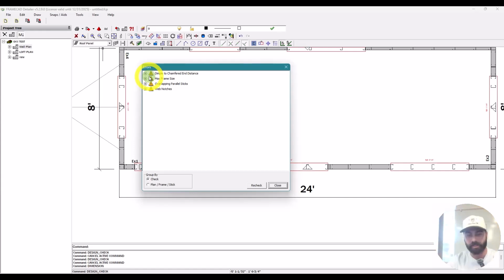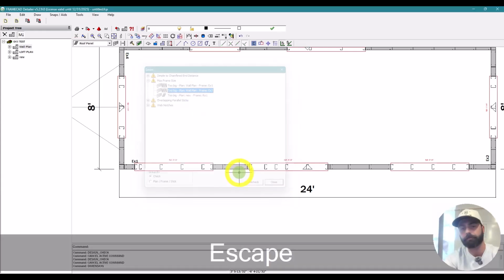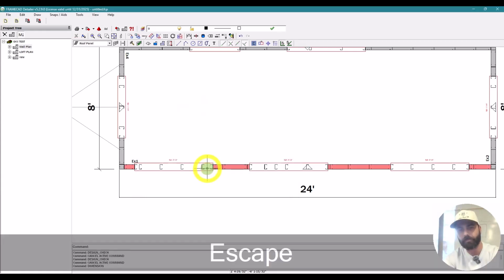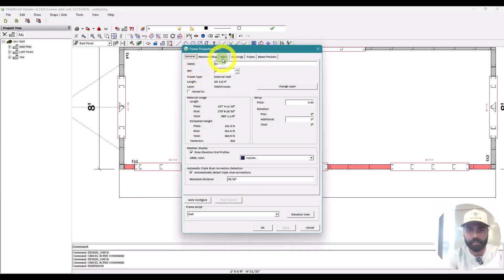All right? And if you were to look at this panel here, we're at 400 pounds, 380 pounds. So if your client's maximum weight was 150 pounds, you could plug in 150 pounds and run that check to see any panel that's over 150 pounds, and we'll typically put oversized panel in the production drawings. We'll put that up at the top so the client or the guy receiving that knows, just so you're aware, there's 2 panels that exceed your shipping requirements, and that's notated in the drawings. This thing's probably a little bit of a mess.